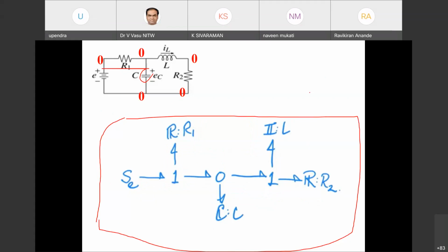any combination system. If you know what is an effort and what is the flow, what are the different junctions which are going to occur, and what are the compliances which are going to be there, you can simply draw this bond graph, and you can simulate what is going to happen in the mechanical systems. Okay, so this is going to be another technique for